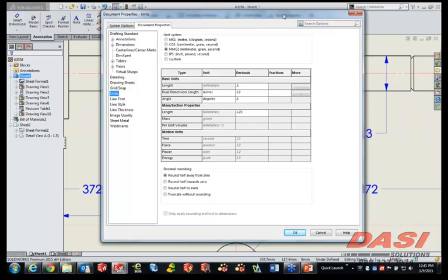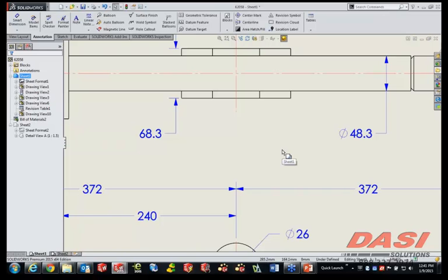We're going to round up on anything that could be above 0.0. So if it's a 0.1, we're going to round up. The reason we do those kinds of things is because in wiring and piping, you'd always want to cut it longer than it needs to be, never shorter. So rounding isn't necessarily always going to be, once you get to 0.3, you're going to round, or 0.5, you're going to round up. This as a 0.25 would round up to a 0.3, but this as a 0.22 would also round up to 0.3 in the proper scenario. Again, wiring, electrical, and piping, you always want it longer than you need, never shorter.